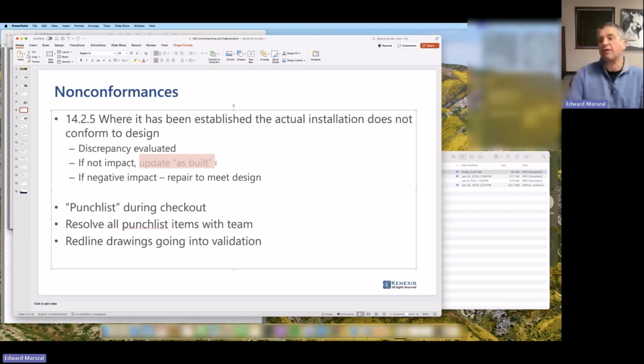So here I was talking about using a differential pressure transmitter. Well, in a differential pressure transmitter, the top is the low pressure and the bottom is the high pressure. But if you took your tubing and you switched what was supposed to be high pressure and what was supposed to be low pressure, that's no good. We can't accept this. We can't as-built it. We're going to need to send somebody out in the field to switch the taps the way that they should have been overall.